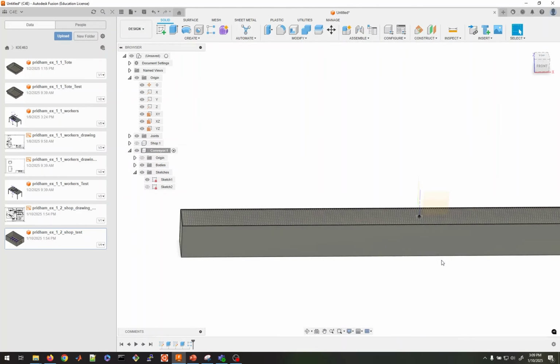That's much nicer than individually doing all of those circles. One of the things we could have also done is a pattern in a sketch to create them all at once, but I didn't particularly want to do that here.